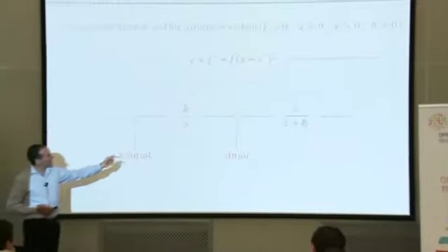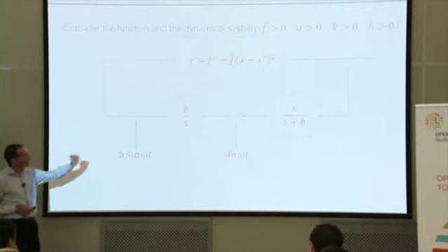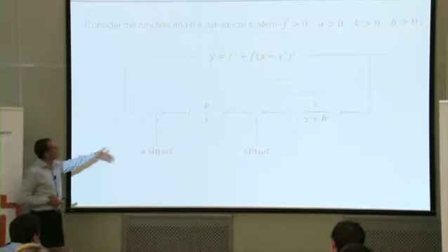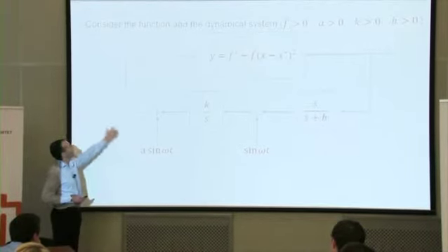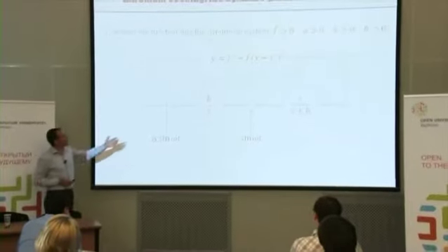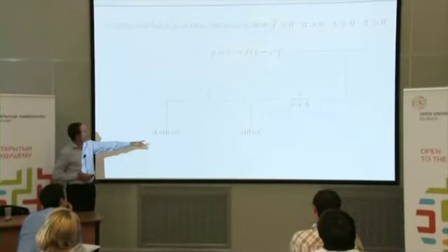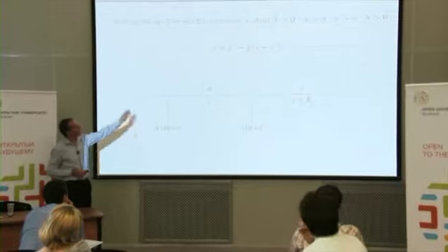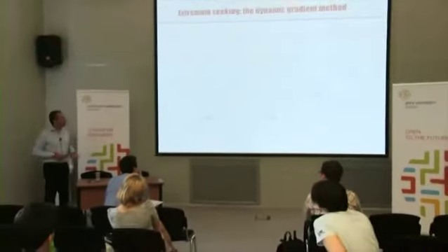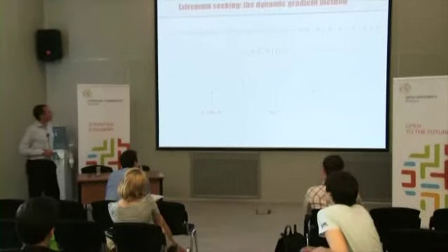You multiply by sin(omega t), you pick some value omega, you integrate the signal, you multiply by sin(omega t) again, and then you close the loop. So you can implement this in a very simple way. This is a low-pass filter, this is an integrator, and these are a couple of external signals. All quantities are positive because in this case we don't have any problem in defining closed-loop solutions.